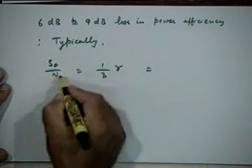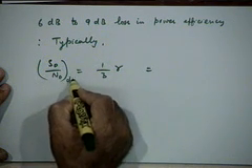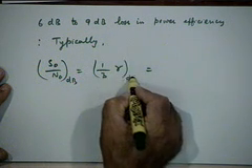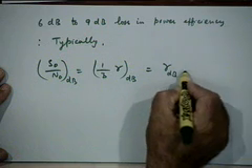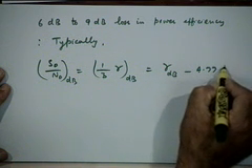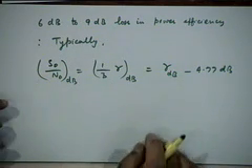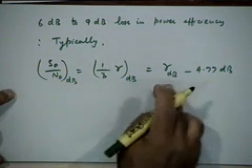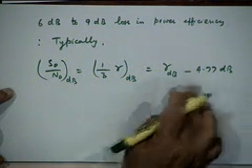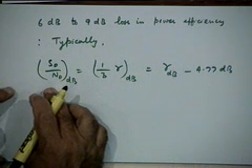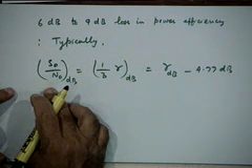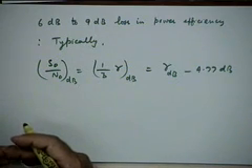If you were to talk in terms of dBs, this in dB would be gamma minus about 4.77 dB. So, you require about 4.77 dB more SNR at the input to get the same output SNR. While 3 dB is a minimum, it will actually range somewhere between 6 to 9 dB. Any questions so far?